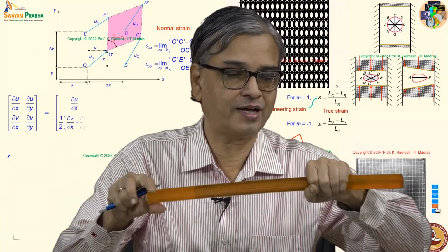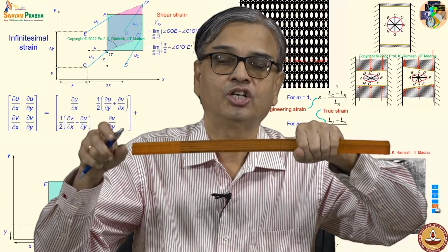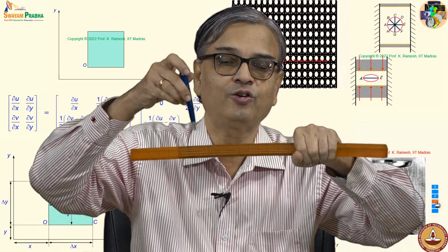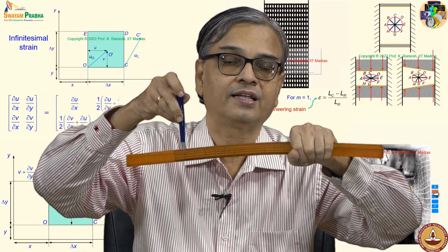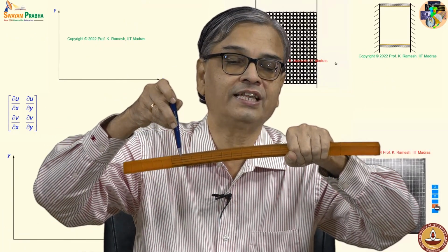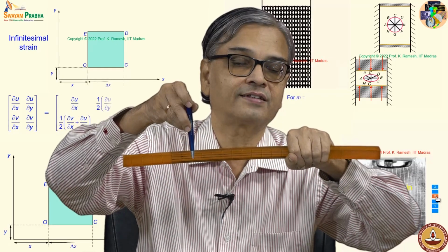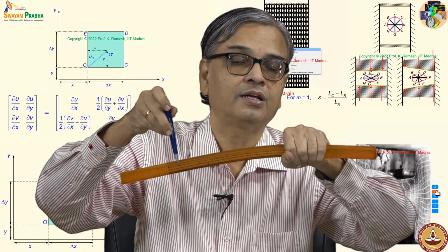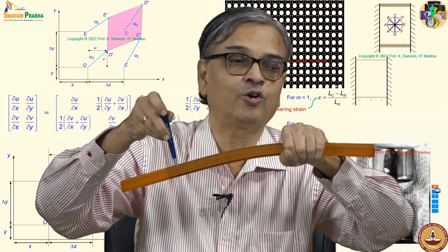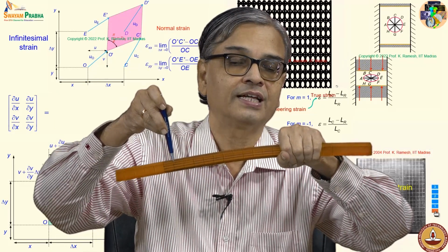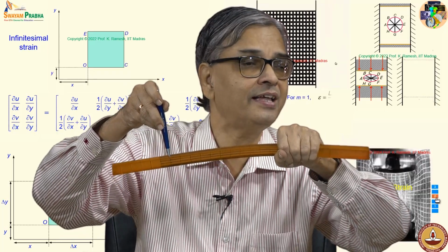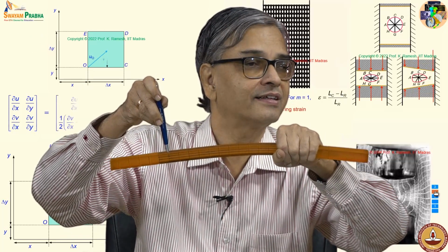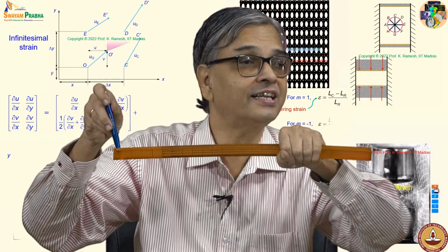And if I take a cantilever like this, let me see how many of you have a look at it. See, this is a very soft material, so it sags even with the applied load. This is the free end. I put a load somewhere in between. So, what happens to the region from the front to this? It is resisting the applied load by bending moment and shear force, and in this section, there is no load, but still it is having a rotation. Can you see that? And this rotation is a rigid body rotation.